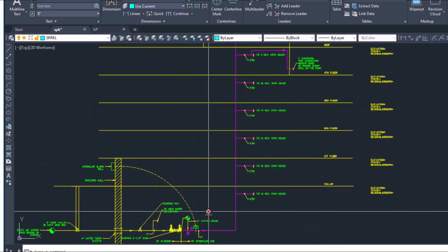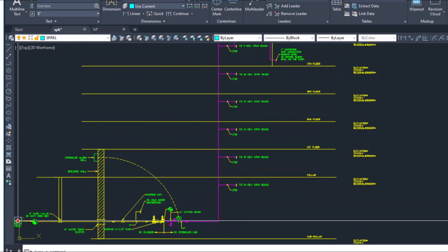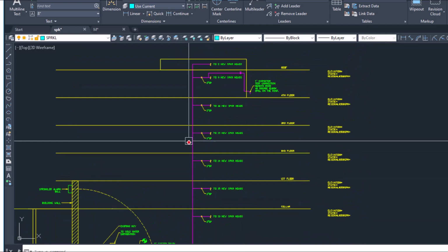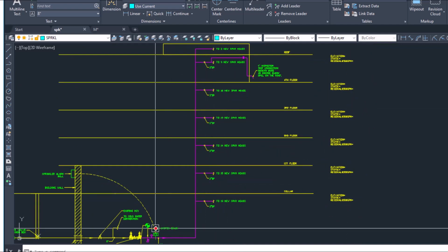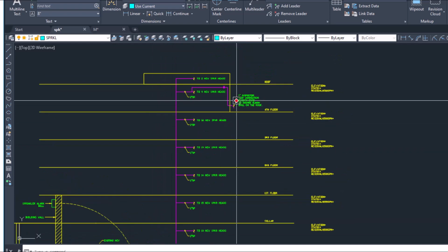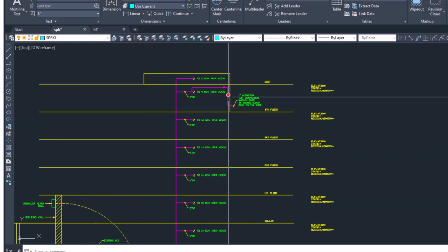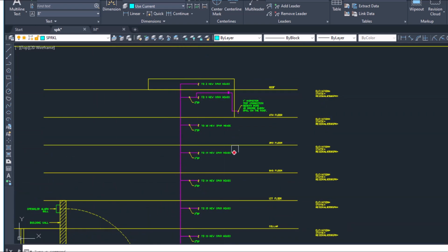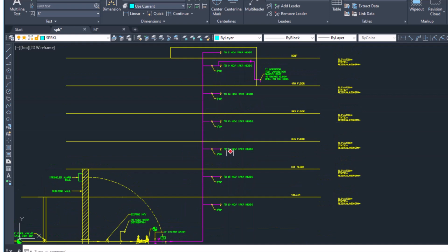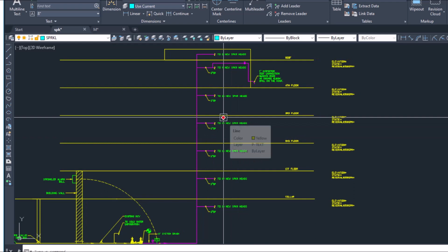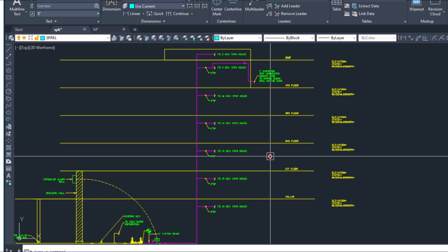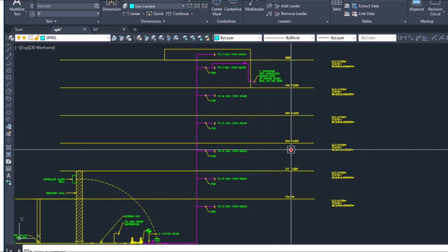So once the system is installed, they would open up all the valves to allow the street water to come in and fill up the system. If it's completely closed off, the air wouldn't allow the water to fill up the system. So you have a test tee here that would be opened up, and that would allow the water to fill up all the way up to the test tee. So now you have more sprinklers that are closer to a water source, which means that if there is a fire, the water would discharge sooner out of that sprinkler head, which would help extinguish the fire sooner.